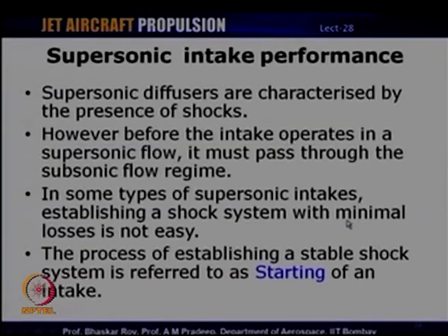Now, supersonic intakes, as we have seen, are characterized by the presence of shocks, but these intakes have to operate right from very low subsonic speeds all the way to supersonic speeds, which means that we will have to establish a shock system as the intake reaches supersonic speeds. And this is often a bit of a problem, trying to establish a stable shock structure.